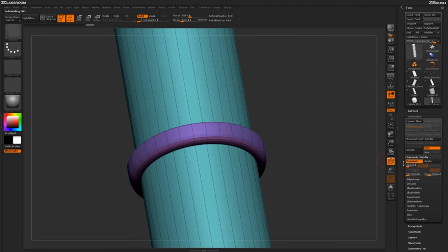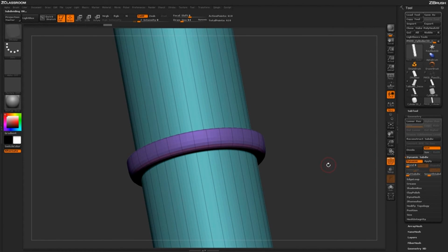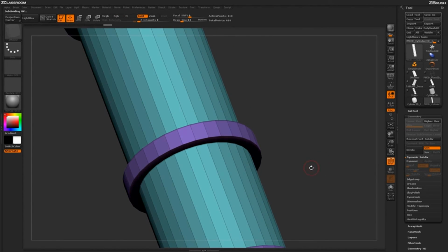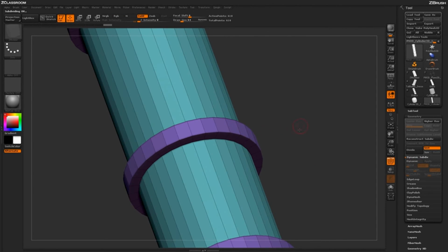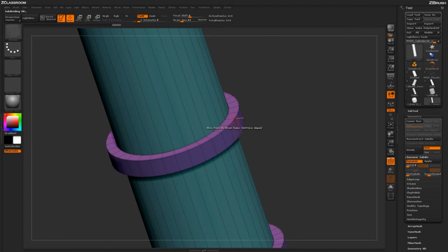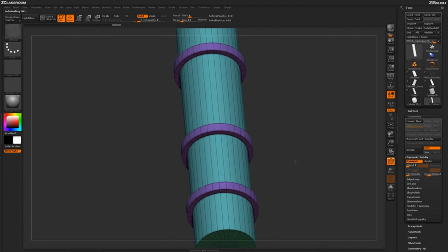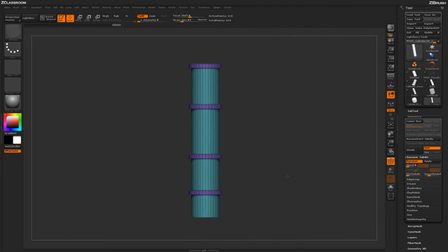Now, when you're using dynamic subdivision mode, you can toggle it on and off to see your original cage versus the actual dynamic subdivided one. There's a hotkey for this, and it's just Shift D and D. So you can come through and just hit Shift D to automatically turn off dynamic subdivision, or D to turn it back on. So this is helpful if you're creasing areas on your model, and you may not be able to select an edge precisely, so you can switch out of dynamic mode, apply that creasing to that area, and then turn dynamic mode back on.